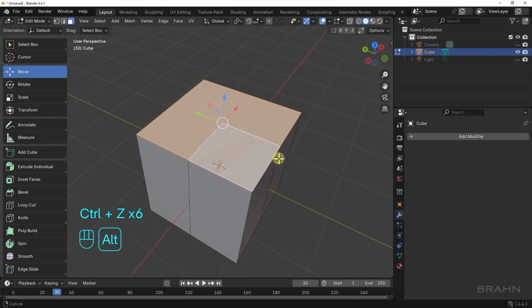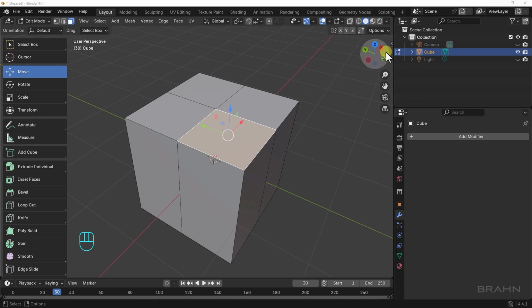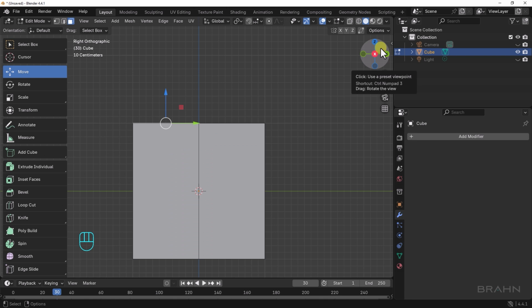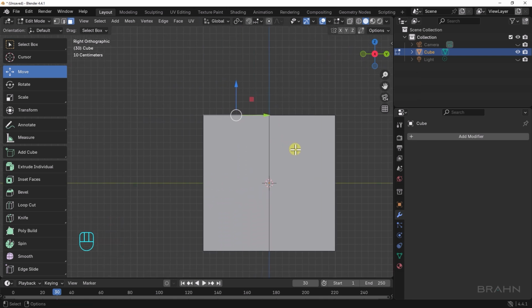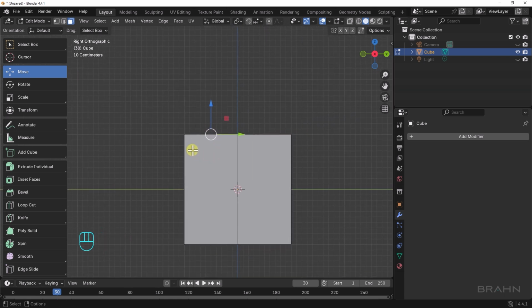Select the upper face nearest to you like this, with a X or red axis going from front to back in your view. Click on the X in the navigation gizmo in the upper right corner of the 3D viewport like so. This will give you an orthographic view of the side of the cube. Position the view to the lower left a bit to make some room. Then with the top face still selected, click and hold the Extrude tool and select Extrude to Cursor. When you do this, nothing happens at first. Position the cursor a little above the selected face and left click.